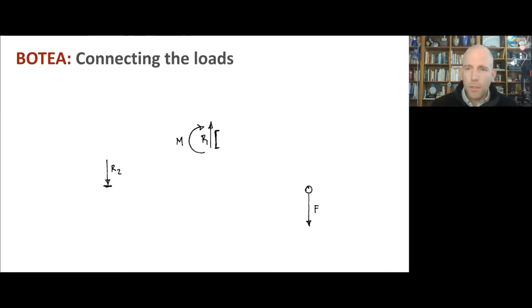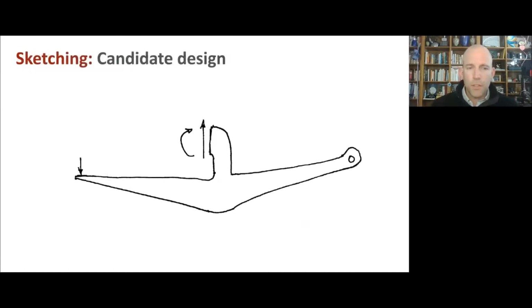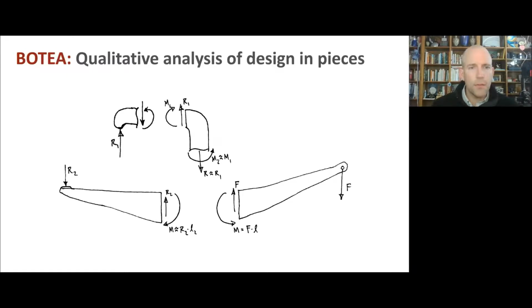I'm going to just talk about a couple of variations that I happened to work through when I was working on this problem. And here's one. And we saw this in several of our designs with a common overall shape. And the logic of the shape becomes clear as you break it into pieces and look at some qualitative free body diagrams. So first, we've got this bit that we've already talked about. We've got this offset load, so this is kind of a cantilever. And we want some finite area to touch the table. We don't want to scratch our nice table.